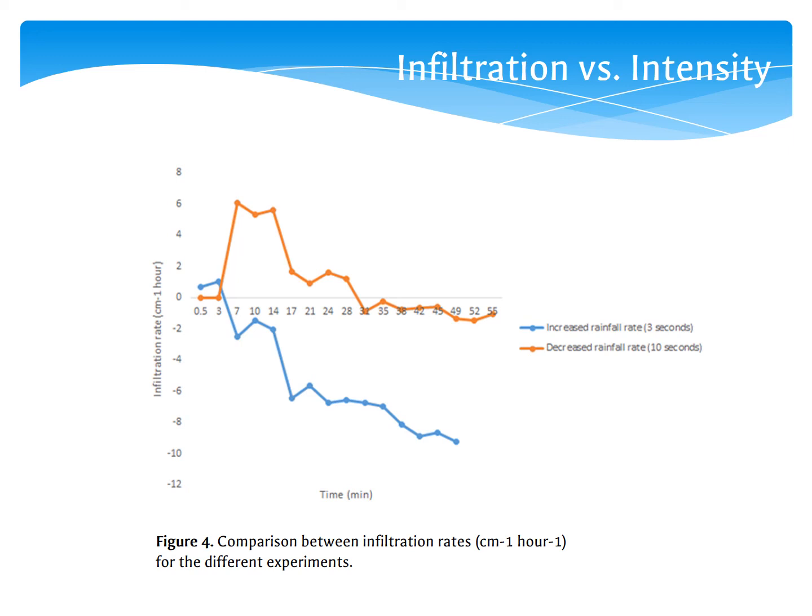Although a faster time to saturation is expected and confirmed by literature, these results are influenced significantly due to the second experiment occurring on already saturated soil. Therefore, this acts as a major limitation in comparing erosion rates with differing rainfall intensities and decreases the accuracy and credibility of our results.